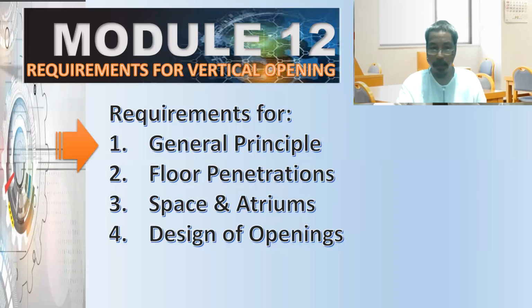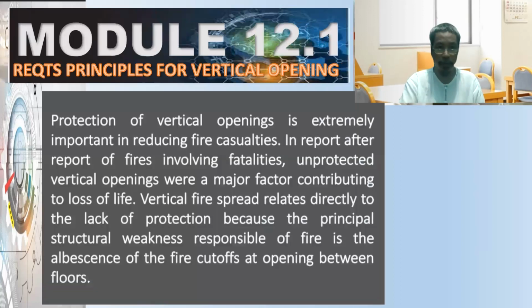So let us proceed with the general concepts and principles. Requirements, principles for vertical opening. Protection of vertical opening is extremely important in reducing fire casualties. After reports of fires involving fatalities, unprotected vertical openings were a major factor contributing to loss of life. Vertical fire spread